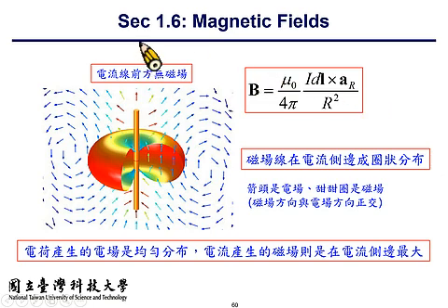Then the cross product of the two is 0. So the magnetic field distribution is not spherical in the space. It's not homogeneous in the space. It actually looks like a donut. So it's the same on the side, and it's strongest on the side. And it becomes smaller and smaller when your observation point is moving to the front or the back of the current source. All right, so as the figure suggests, it looks like a donut or what?